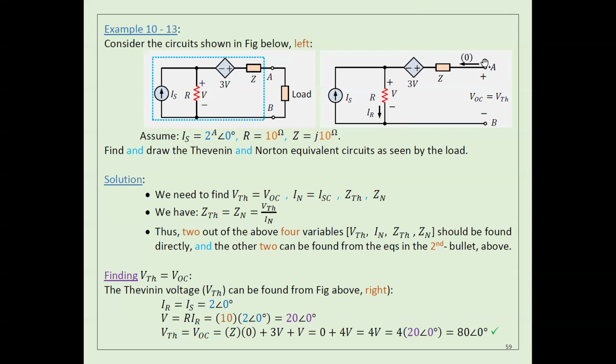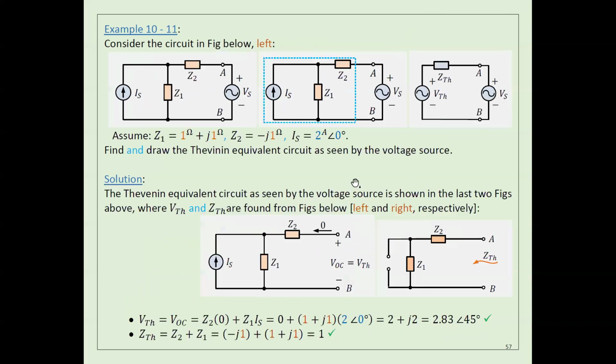I want to calculate the voltage at this point here, V7. Okay, I'm sure most of you will be confused here. Someone can say, and that's wrong, someone can say that because the current here is equal to 0, the voltage here equals the voltage here. Similar to what we did here. So in this example, once I found the voltage here, I said that because there's no current in this impedance, the voltage here equals this voltage. That's what I did here.